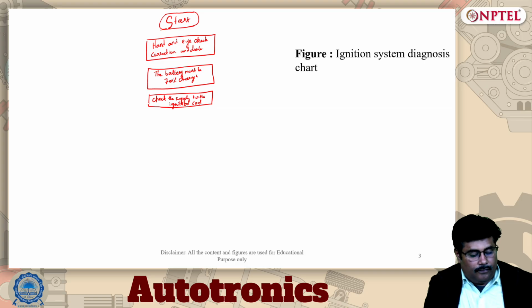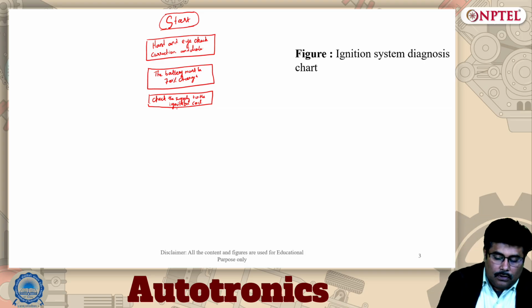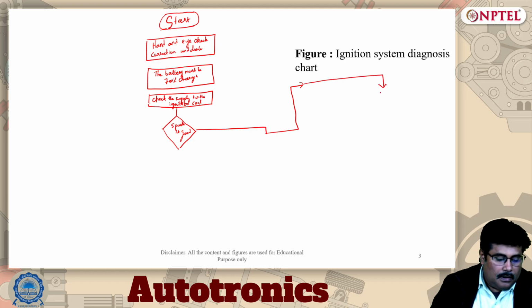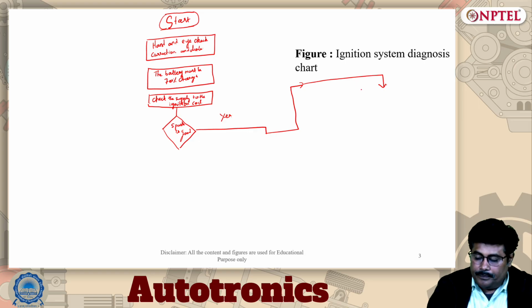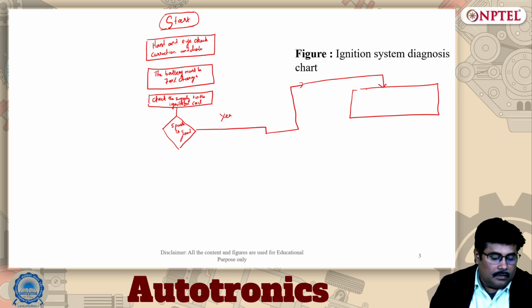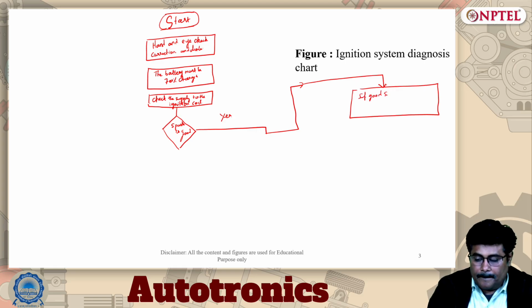Now, if the spark from the coil is good, then check the HT system for tracking and open circuit.